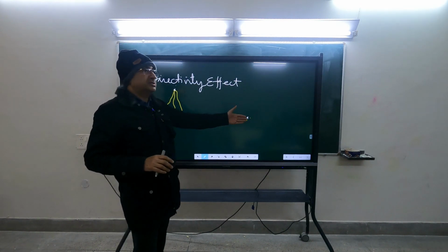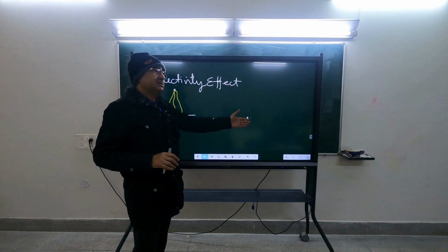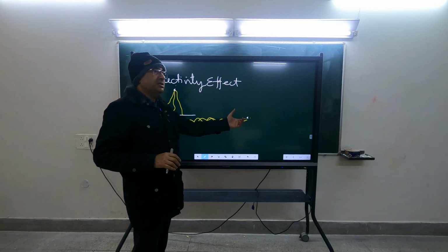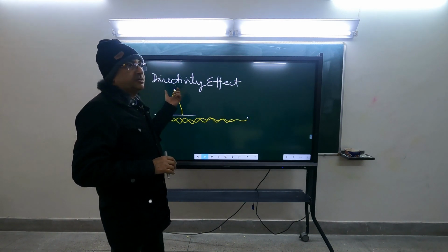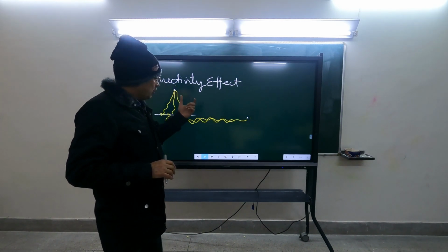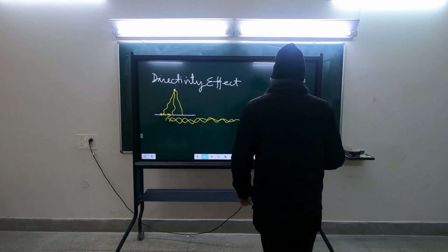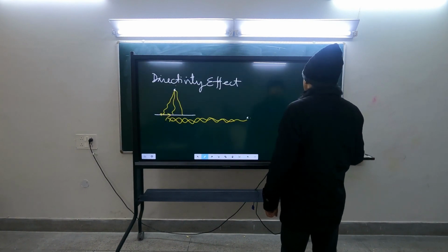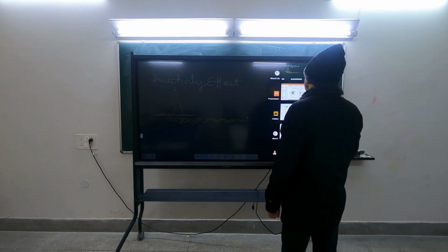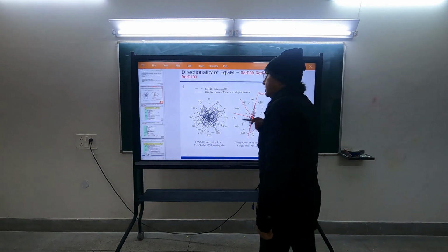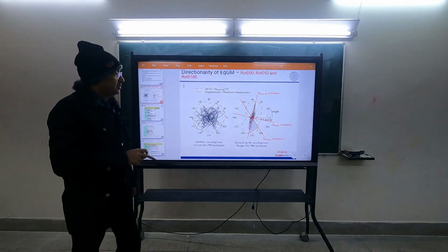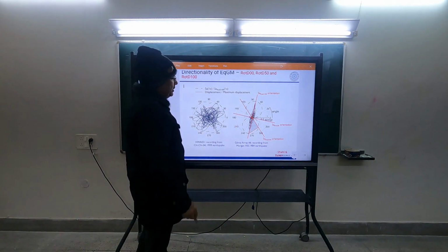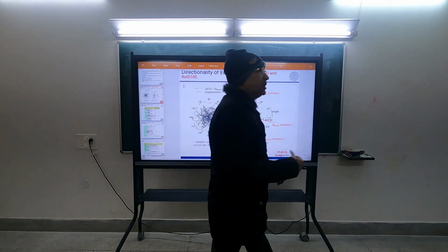So those sites which are along the alignment of the fault will be experiencing a different type of earthquake than these. In one particular direction, the earthquake intensity may be much stronger, while the component in the perpendicular direction can be much smaller. This is called the directivity effect. So here you have a significant directivity effect. You can also call it polarized ground motion.